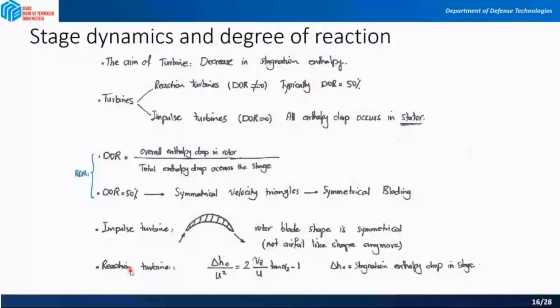Now, here we will define one coefficient called the Zweifel coefficient. And this Zweifel coefficient has a direct impact on the sizing or weight of the engine. This Zweifel coefficient is used to determine the blade spacing as well. So this is showing the blade spacing to you. If you have your blade-to-blade view, the space between two consecutive blades is called blade spacing. How we are going to see it in this slide.